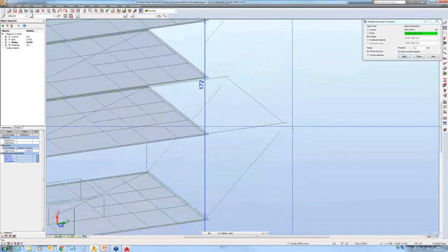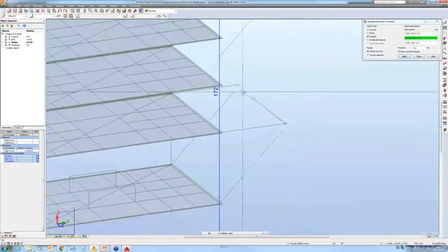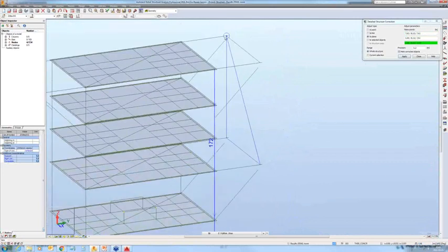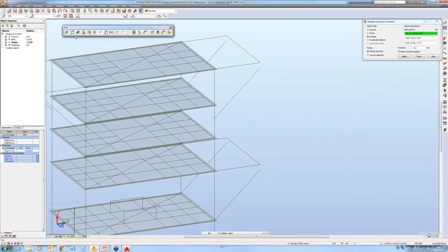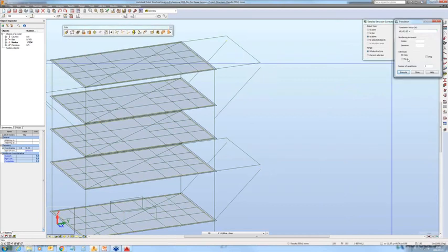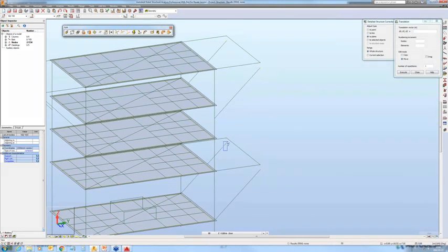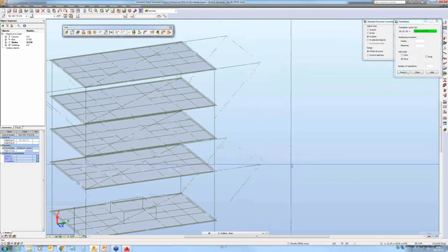struts with the platforms. So I'm going to just indicate 3 points, and I will change the range so that it matches the distance, and you can see that short cantilevers are gone, and all I need to do is move these 4 points to their correct locations. So I will move that. I need to select 4 of them: 1, 2, 3, and 4. Okay, 4 of them, and then just move them.